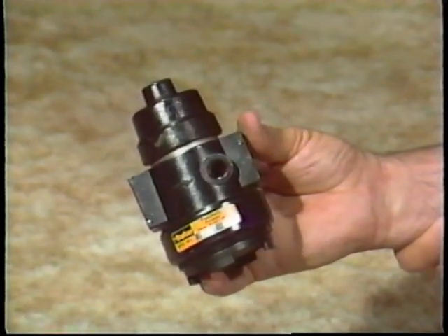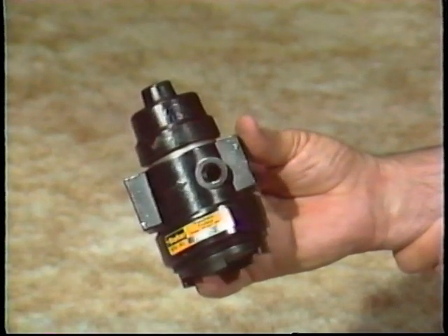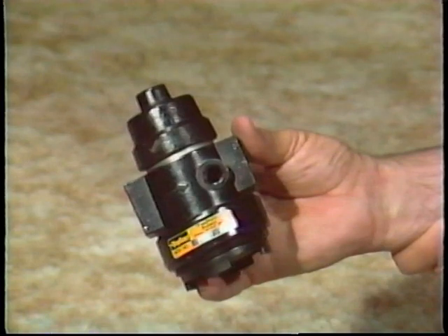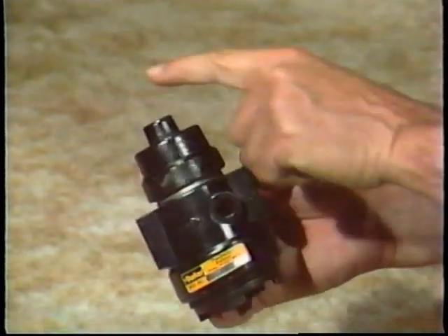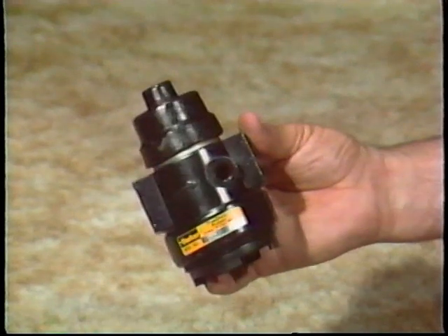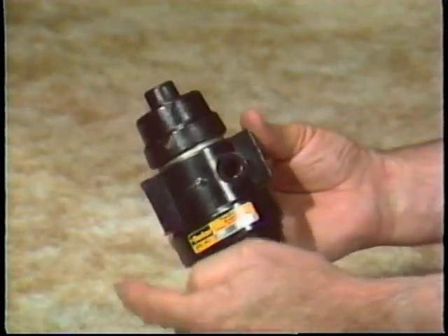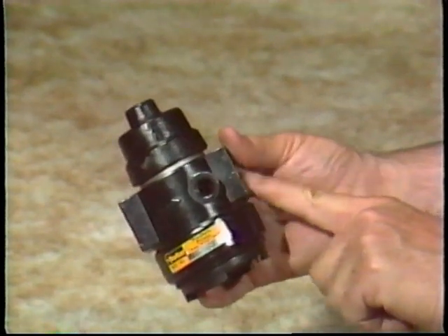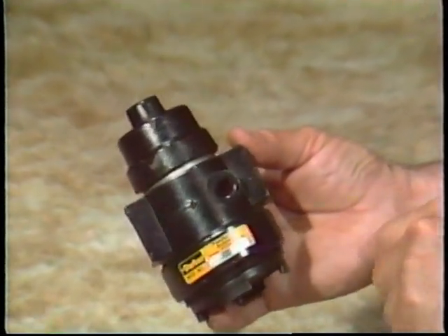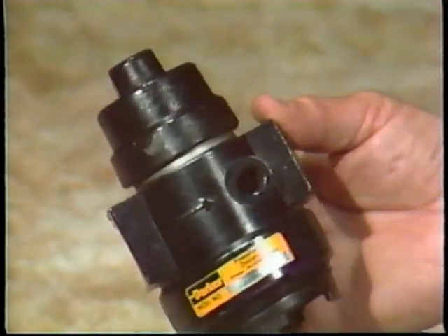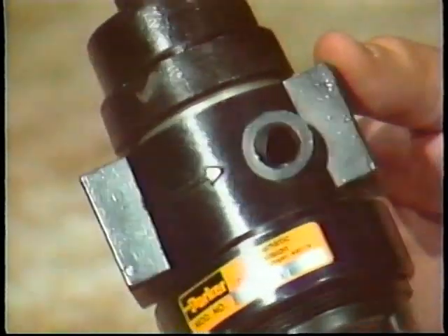In some applications, it may be necessary to readjust the air pressure from a remote location, say from a main control panel. One way this is done is with what's called a pilot-controlled regulator. This is a pilot-controlled regulator. You can see it has a slightly different shape, and instead of an adjusting knob, we have this pilot port here, where the pilot supply line would be connected. Here is the input port, and this is the output. This small arrow cast into the side of the valve body indicates the correct direction for airflow.